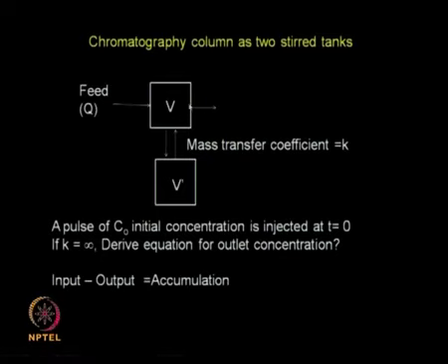Can you derive an equation for the concentration of the solute leaving the first tank as a function of time? The problem here is different from the problem before. In the previous problem we assumed K equal to 0, that means tank 2 is not contributing anything, but in this second problem we are assuming K equal to infinity, that means there is a complete exchange, there is no resistance at all for material to get transferred from tank 1 to 2 or tank 2 to 1.